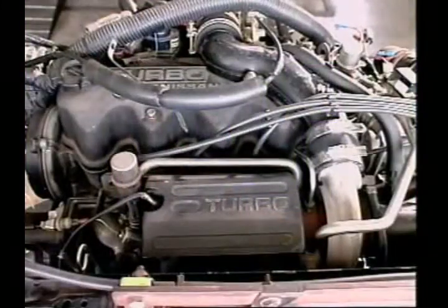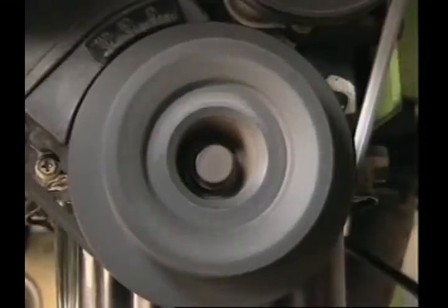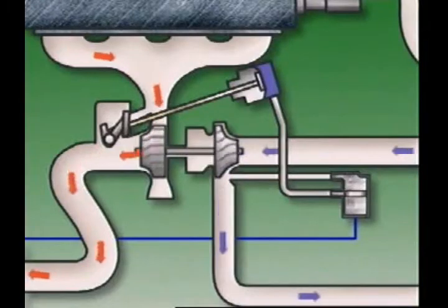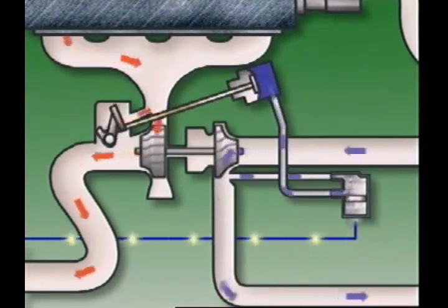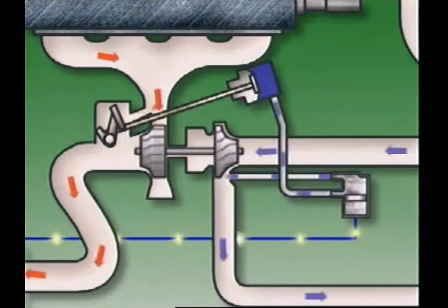A turbocharged engine is different. Simply retarding the ignition could increase the already high temperatures at the exhaust-driven turbine. But reducing the boost pressure at the same time brings detonation under control quickly.